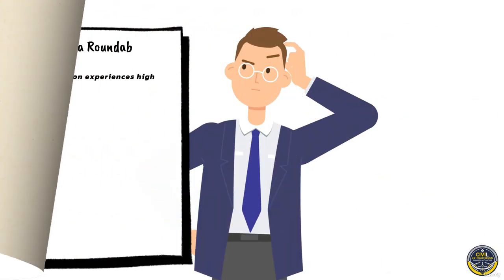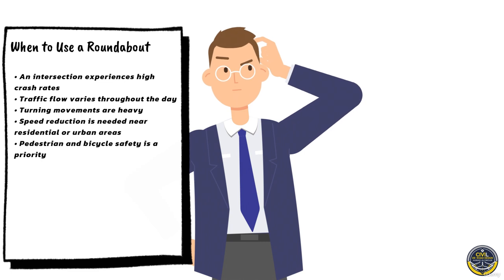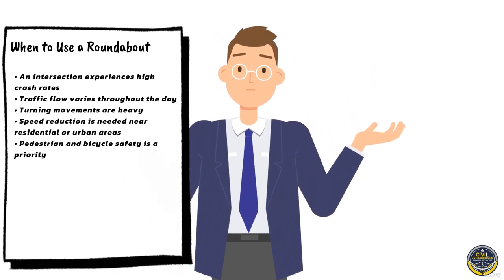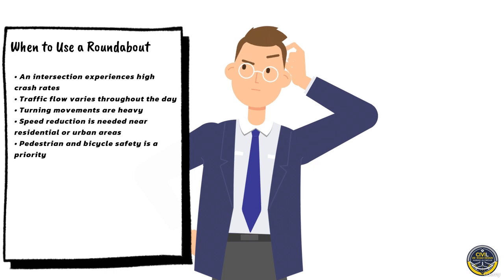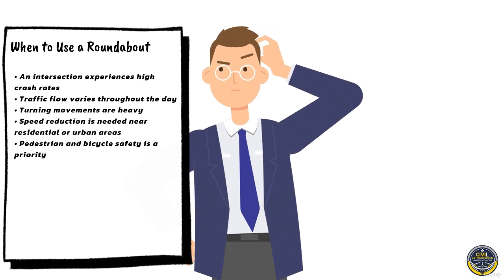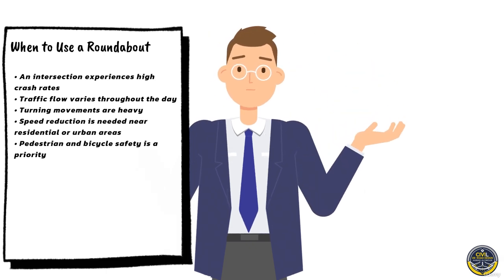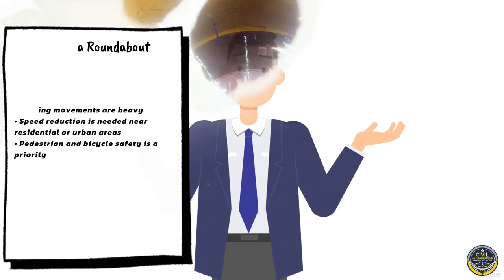When to use a roundabout? Roundabouts are ideal when an intersection experiences high crash rates, traffic flow varies throughout the day, turning movements are heavy, speed reduction is needed near residential or urban areas, or pedestrian and bicycle safety is a priority.